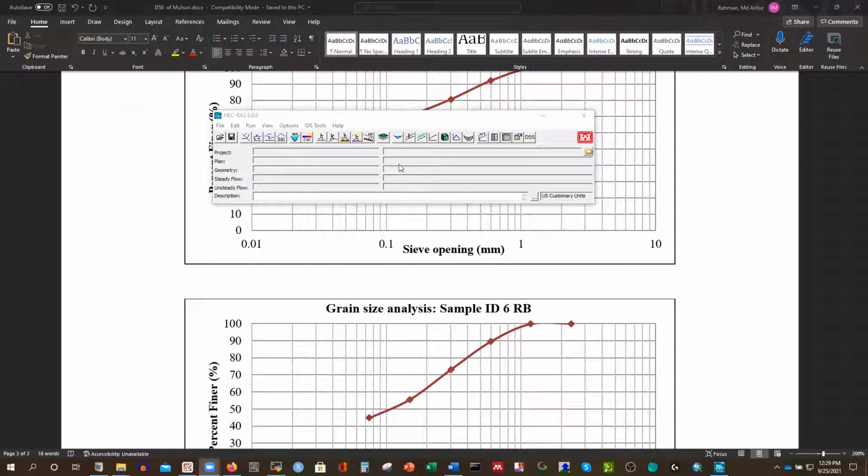And in the third part of the tutorial series, I demonstrated how to insert the bridge information and how to insert the piers of the bridge. We maintain a certain span length and vertical clearance. So we know how to import geometry from survey data, and how to calculate the 100-year, 50-year or 25-year flood water level and flood flow rate at the same time. And you know how to insert the bridge. So now everything is ready.